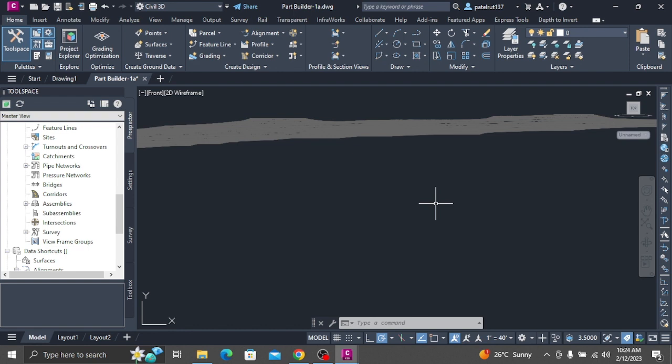Scroll to the right until you see the SFL and SFW columns. Change Constant to List for each of these columns. Then change the view to Values. Using the same procedure that was used for SBSL and SBSW, add values of 36, 48, 60, 72, 84, 96, and 108 for SFL. Add values of 24, 36, 48, and 60 for SFW. These values are now controlled by lists that can ultimately be manipulated from within Autodesk Civil 3D when the part is in use. Click OK to close the Edit Part Sizes dialog box.